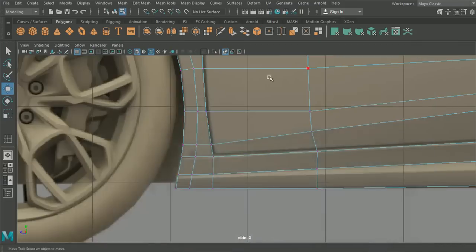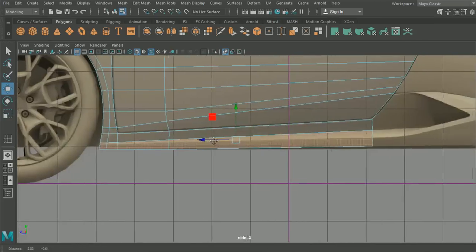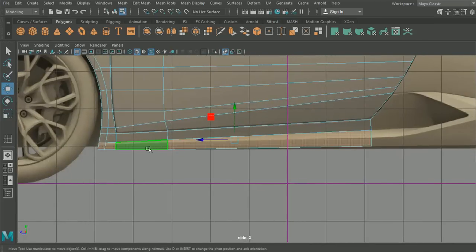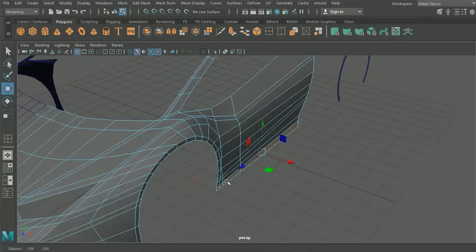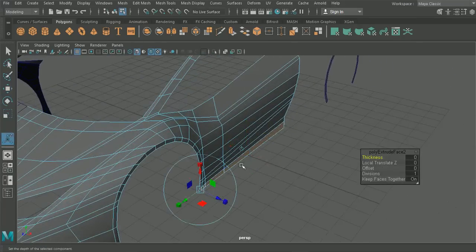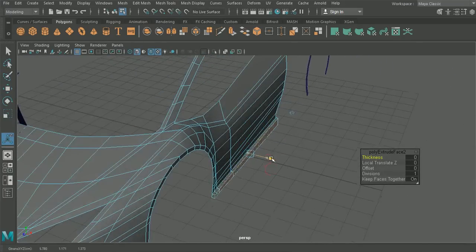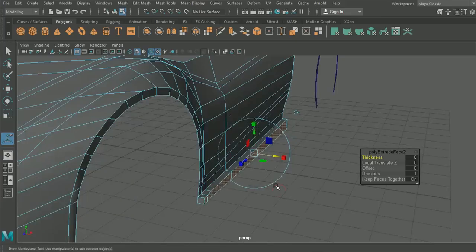Okay. So what we'll do here is we're going to hit our face and we're going to click on all of these. So we're going to right click on our model, select face. We're going to right click on all these sections here to highlight them. We're going to extrude them just like we do with the different edges. So we're going to hit Control E. We're going to come out on the world again and see if we can pull this.